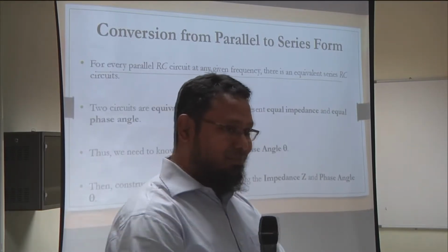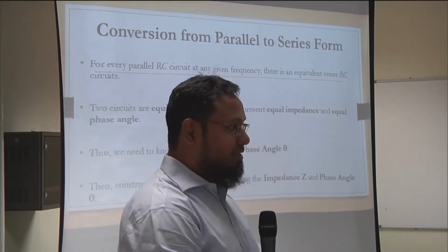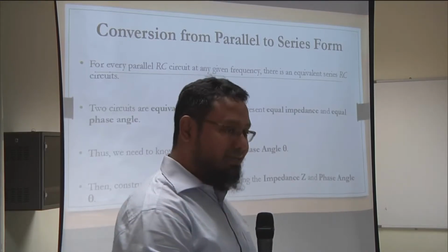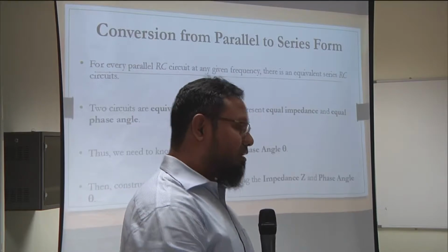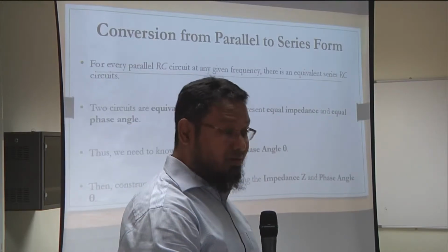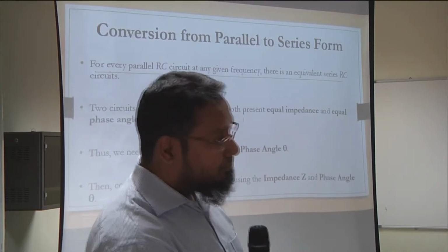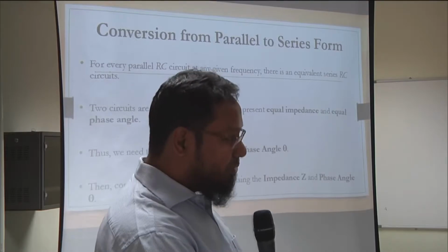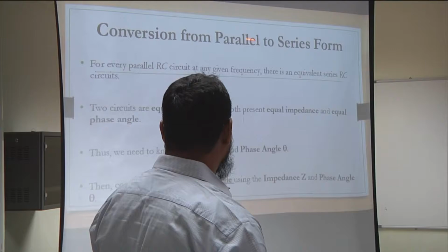And the imaginary part of that equivalent impedance is going to be a reactive element. Depending on the sign, that can be represented as an inductor or a capacitor. If it's a positive imaginary part, you can represent that as an inductor. If the imaginary part happens to be negative, that's going to be a capacitive reactive element. And that's what it's talking about.